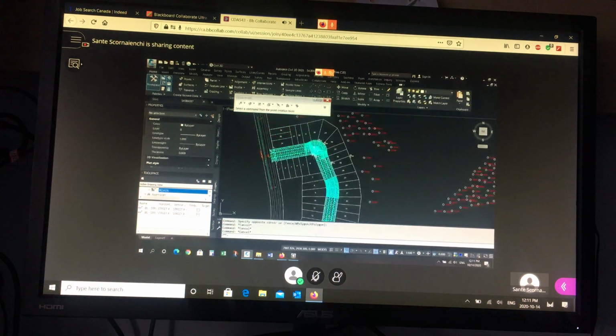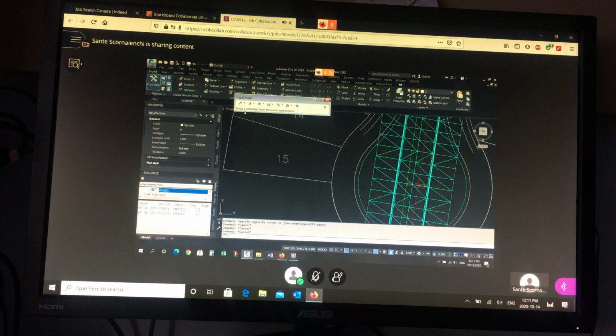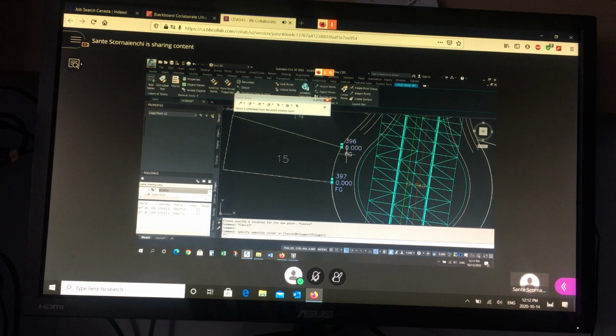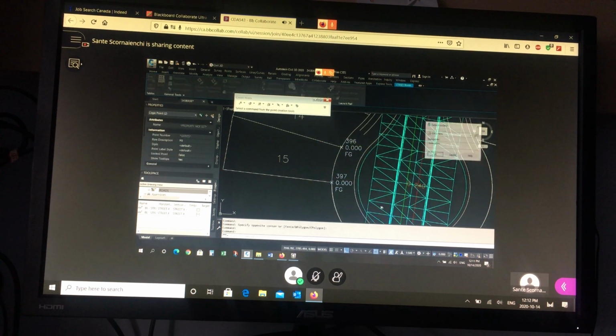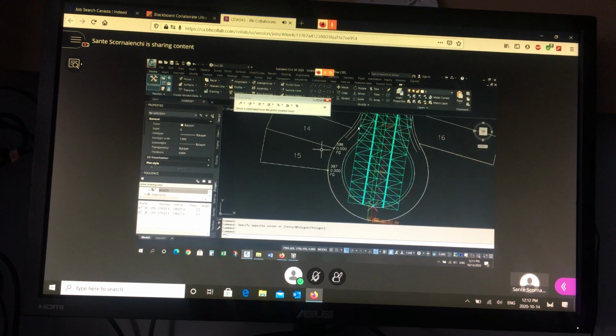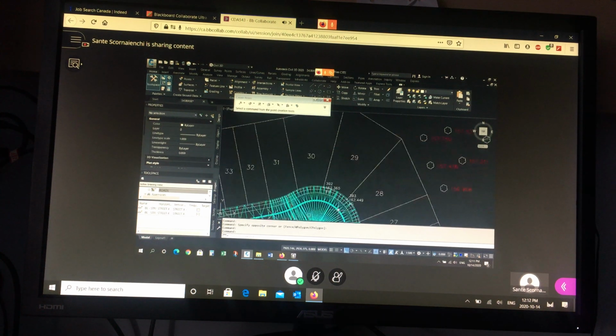Now my front lot corner here, right? My front lot corner here, right here, and here. Right? I want the elevation for these all the way around the cul-de-sac. Elevation from surface. Proposed. Why? Because the model's wrong. It doesn't extend around the bulb like we did it here. Okay, so you have to create that model.